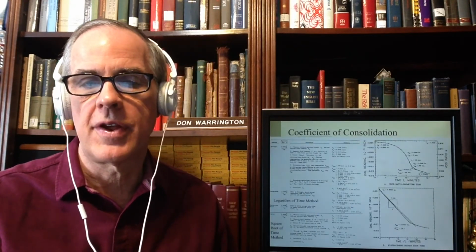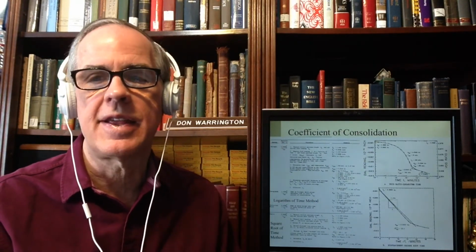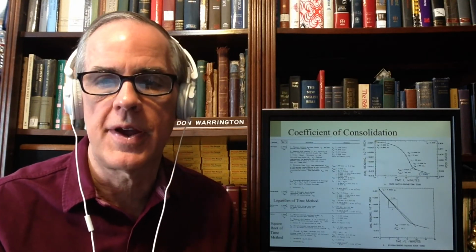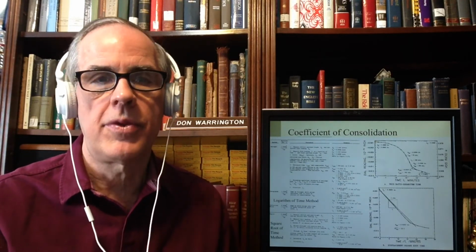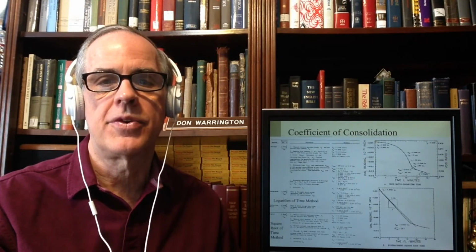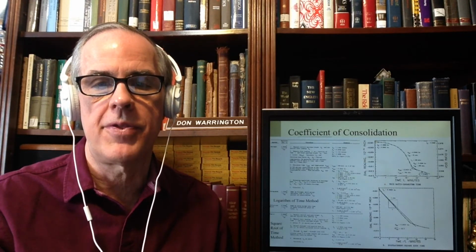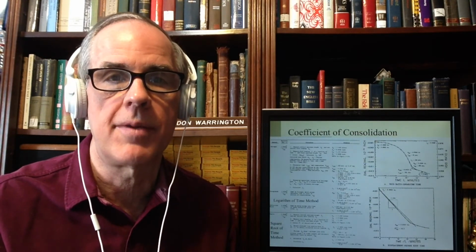The coefficient of consolidation. I have traditionally left this problem for the lab. It's not an easy thing to do for the first-time student, but there are 2 methods that are used. One of them is Terzaghi's logarithm of time method, which has been modified by different people, and the other one is Taylor's square root of time method. And I think both Veriot and your Soils and Foundations Handbook discuss this in some detail.